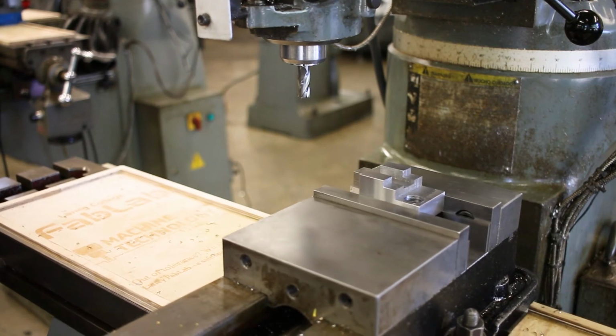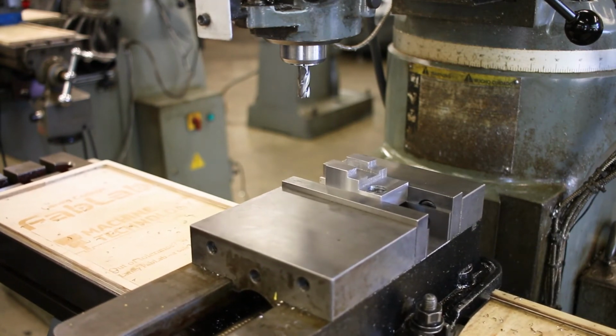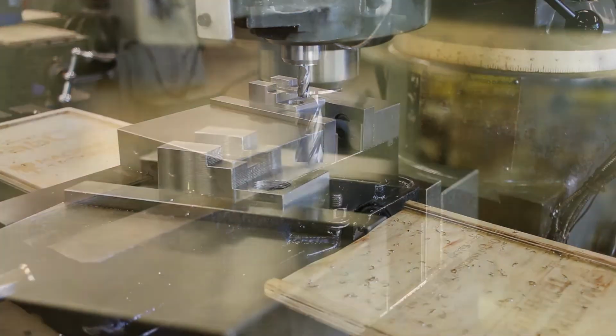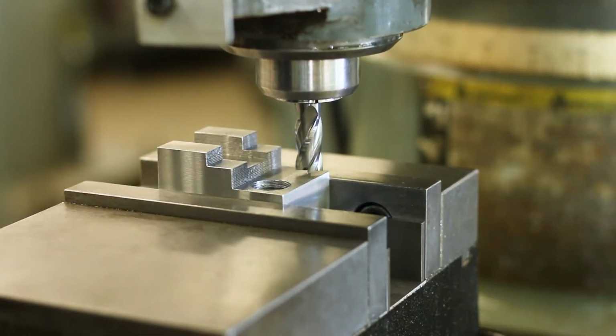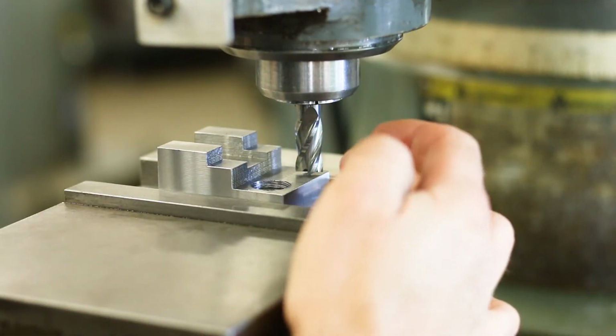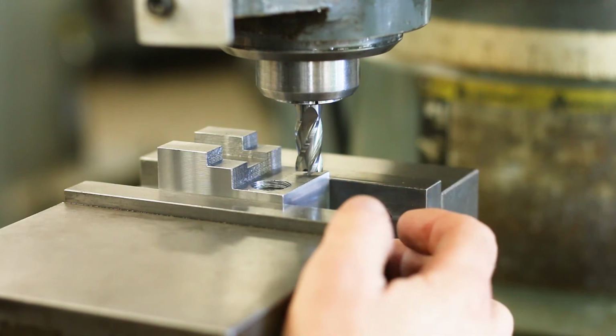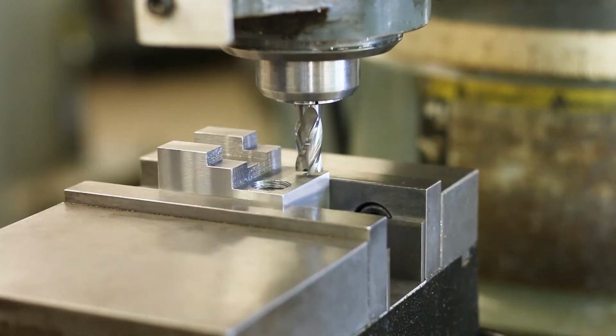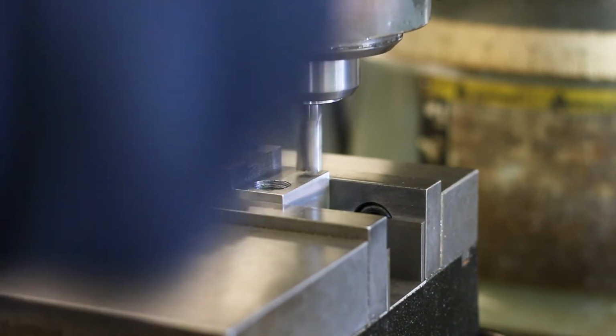Okay, let's position this for the first cut. I'm going to get this a little bit closer. We are not going to do a static touch-off with this thing. Definitely not. It's way too brittle, and we could easily chip it if we just touch it to the material without it spinning. I'm going to go ahead and turn it on, adjust the speed.